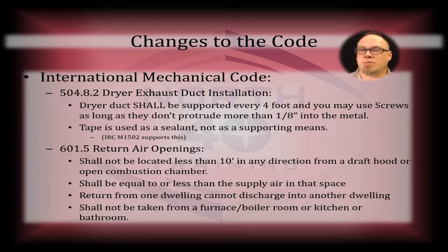You can't draw combustion air from a bathroom. So that means that a power vented water heater and a single pipe 90% furnace or any 80% furnace or boiler may not comply with that application without doing major structural changes to that downstairs area. Electrical wiring may not comply. Okay, so those things make a difference.